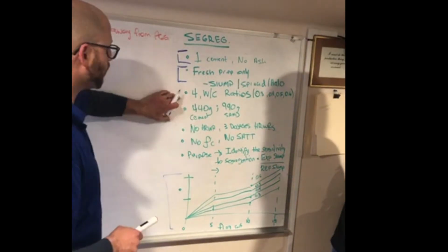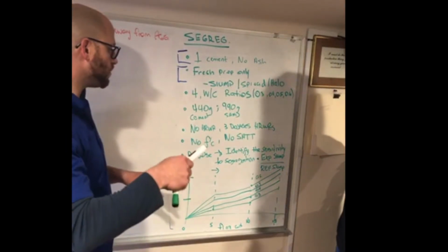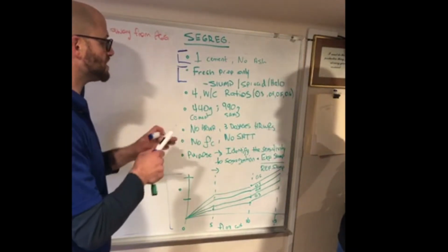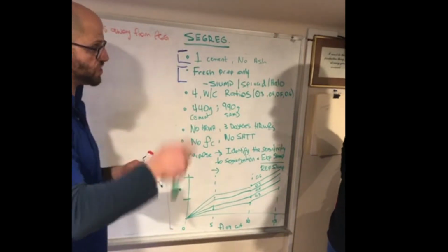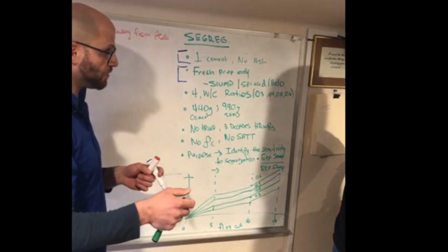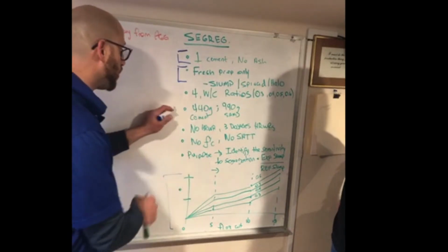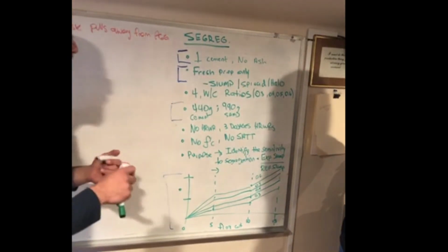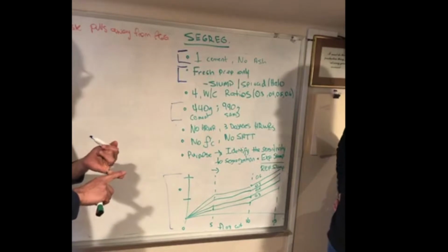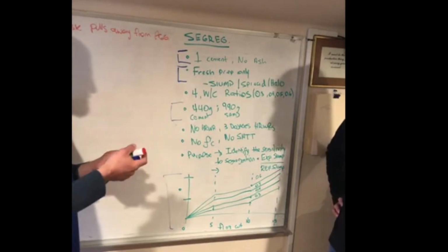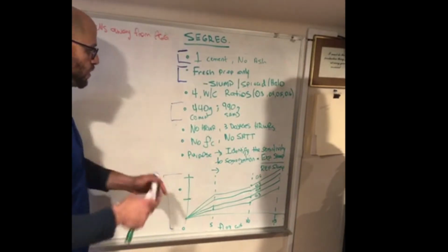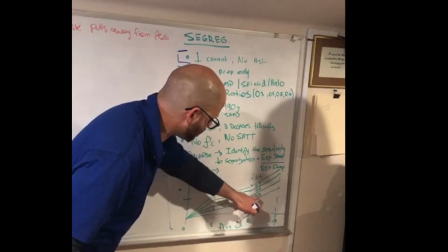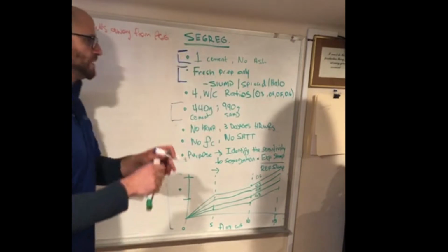Okay. So 4 mixes for every 1 water cement, or 4 mixes plus a reference on each one of those mixes with changing dosages of the high-range water reducer. So we're going to keep 2 things constant: the cement and the sand. We're going to be using ASTM C1260, 1567, and then what we're going to change here is the water cementitious ratio from 0.3, 0.4, 0.5, 0.6.